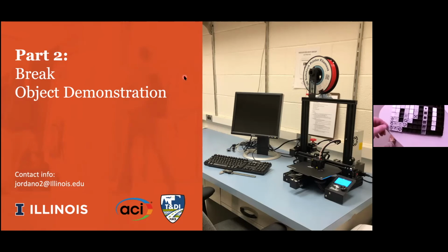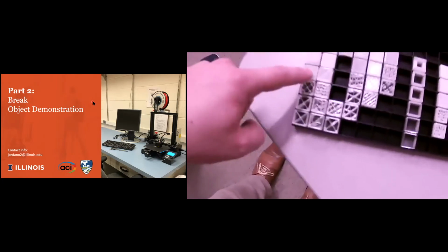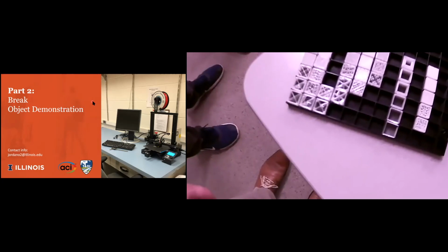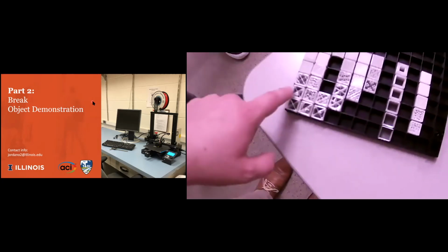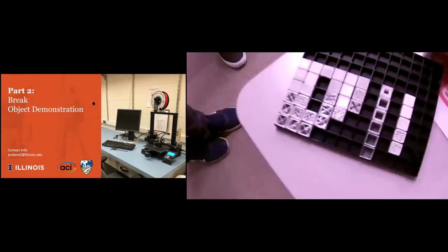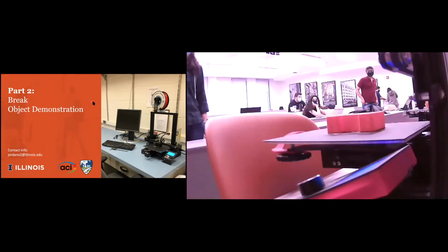So as we can see, is it good on Zoom? Yeah. We have different types of infills. In that case here, that's 5% infill all the way to the top, 100% infill. We can see that at this value of infill, which is 50%, we get pretty much good mechanical strength for parts. But obviously you increase your printing time a lot. So that's what kind of different infills you can use, different designs, geometric shapes, or percentage of infill. So how to select it? I would say it's iterations. You do a design, you test it, you select another infill, and that way you can select a good infill.